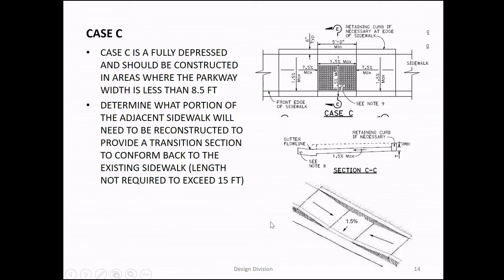Jose, where does that 15 feet come from, is that ADA? It's ProWalk, the 15-foot flare. The ADA and ProWalk are very similar, but ProWalk sometimes is a little bit more lenient. So the slope here, max should be 7.5% or 15 feet if you're chasing the slope.